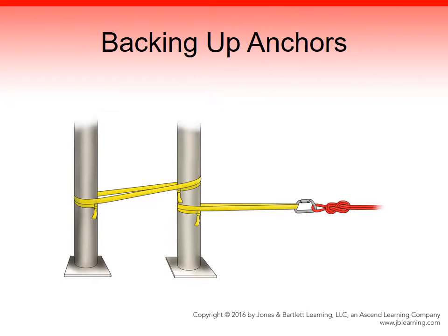Two things must be kept in mind when using a secondary anchor. The secondary anchor must be as strong or stronger than the primary anchor, and the tieback must have no slack that would allow shock loading, which could cause both anchors to fail.